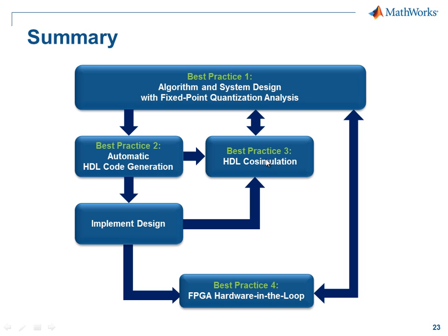And with the last best practice, we have enabled regression testing with FPGA in the loop simulation using HDL Verifier. And additionally, we also had a look at the FPGA turnkey workflow, which enabled us to fully deploy an algorithm running standalone on an FPGA board, where we could take advantage of the audio input and output peripheral interfaces of that specific board.